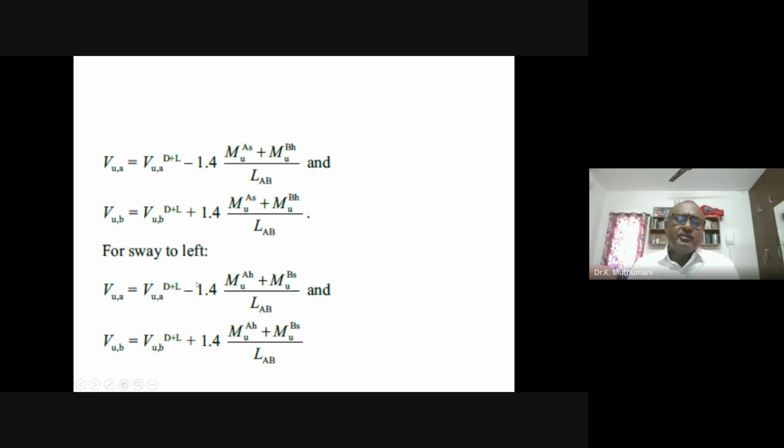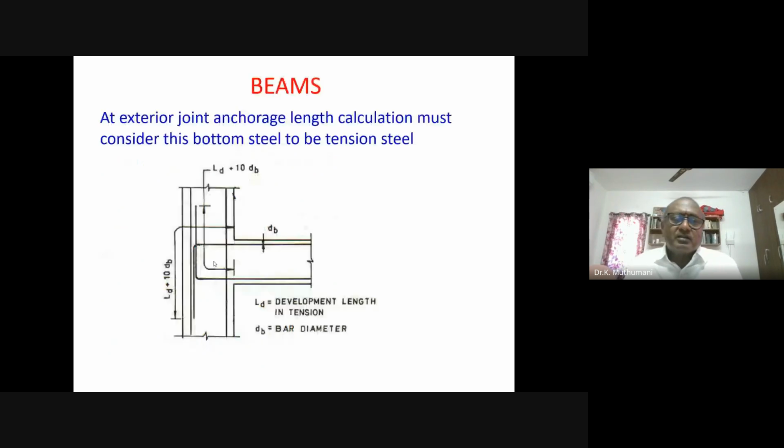So this is an important thing I wanted to note, because most of the time the building fails only because of shear weakness. Because bending moment, most of the time they would have given correctly, and slight variation here and there would have been taken care of. Suppose there is a minor error in this calculation, nothing will happen, because there are still so many factors to take care of. But shear, there is no way to take care. That is why we have to talk about this.